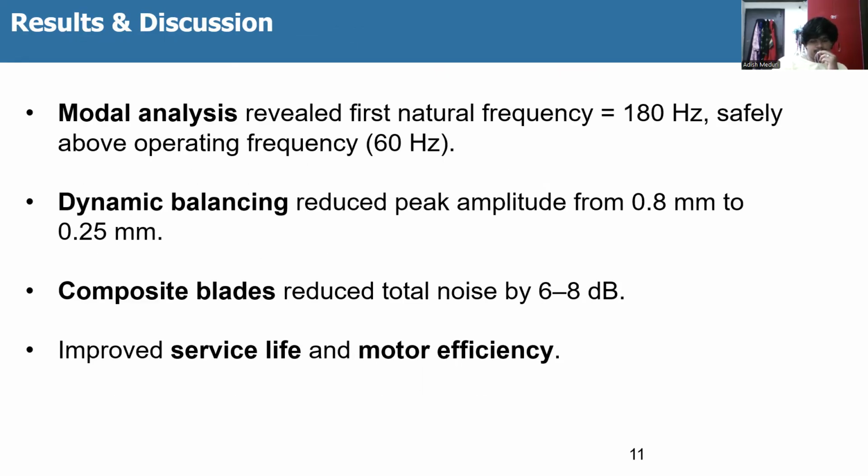Results and discussion. Modal analysis revealed the first natural frequency at 180 Hz, safely above the operating frequency of 60 Hz. Dynamic balancing reduced peak amplitude from 0.8 mm to 0.25 mm. Composite layer reduced total noise by 6–8 dB. Improved service life and motor efficiency.